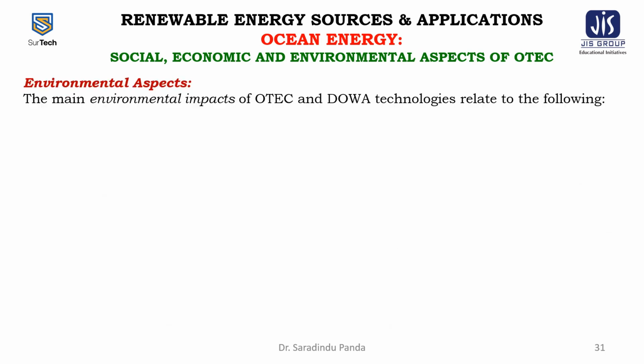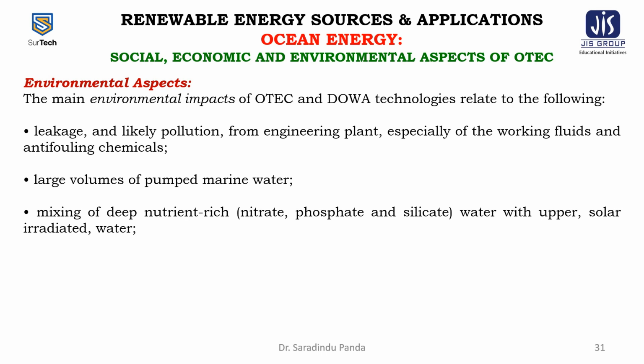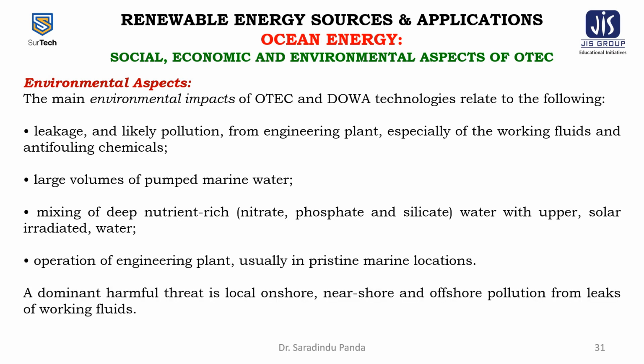Now the environmental aspects. The main environmental impacts of the OTEC and DOWA technologies relate to the following: leakage and likely pollution from the engineering plants, especially of the working fluids and the anti-fouling chemicals, large volumes of pumped marine water, mixing of deep nutrient rich water, that is nitrate, phosphate and silicate, with the upper solar irradiated water, operation of the engineering plant usually in pristine marine locations. A dominant harmful threat is the local onshore, nearshore and offshore pollution from the leaks of the working fluids.